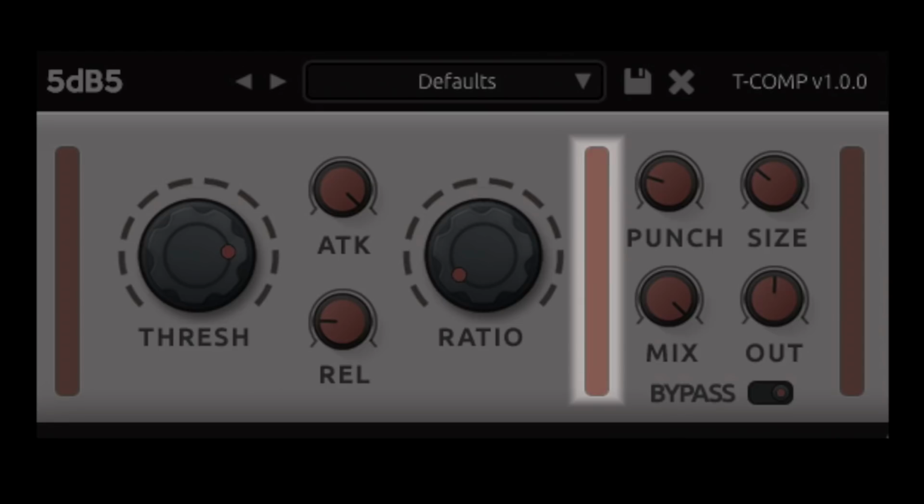There is a gain reduction meter to show you when gain reduction is being applied. However, there is no number reading on this meter, as the amount of gain reduction that is appropriate will be different for each source. This allows you to visualize that gain reduction is in fact happening at the settings you've dialed in, but frees you to use your ears to tell you when the right amount has been applied.